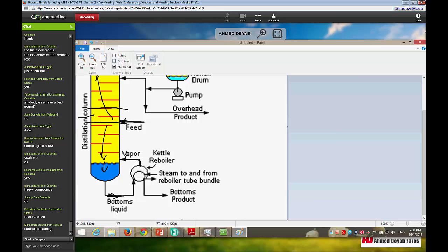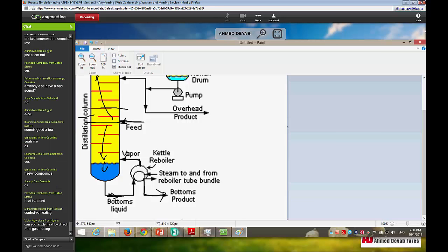And the heaviest component will be heated but still liquid, so I'll separate it as a liquid final product. So here we are doing partial vaporization for only the lighter components. We are controlling the heating steam or hot oil or any heating medium to achieve the boiling point for only the lighter components.